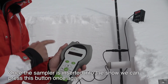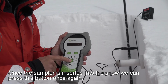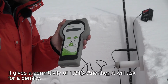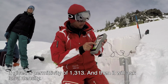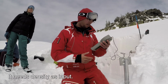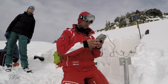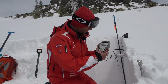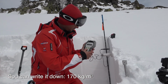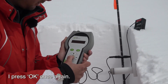All right. Once the sampler is inserted into the snow, we can press this button once again. It is saying measuring. It will say the permittivity is 1.313, all right, and then it will ask for a density. As I said before, it needs density as input. So the density of this layer was about 170, so I can try to write it down. 170 kilogram per cubic meter.